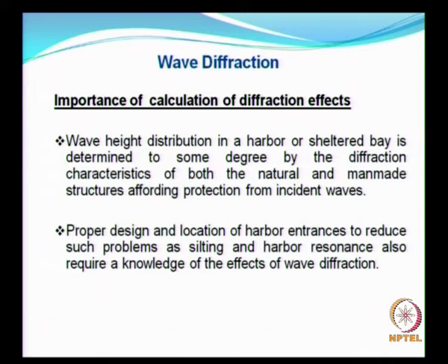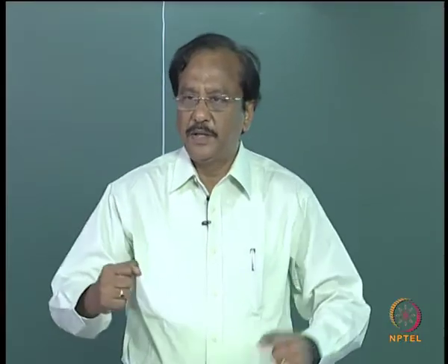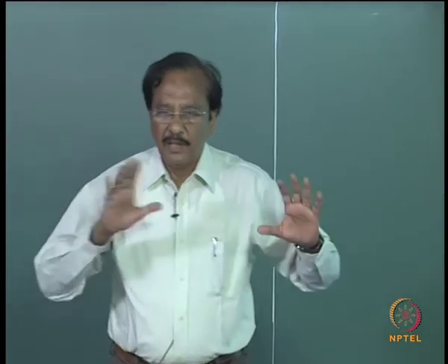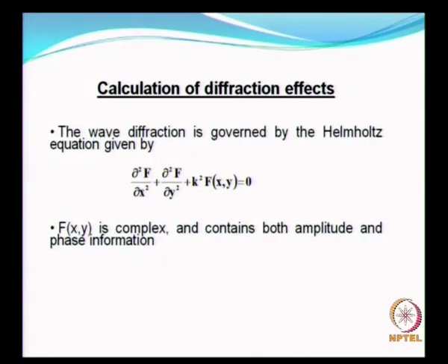So when you plan for a harbor, what you normally do is consider the predominant wave direction, and you consider more or less the long period waves in that area, and you try to align your breakwater and also fix the gap between the breakwaters in such a way that you have minimum disturbance after the construction of breakwaters. So diffraction calculation is not so easy compared to what we have seen earlier in the case of refraction.